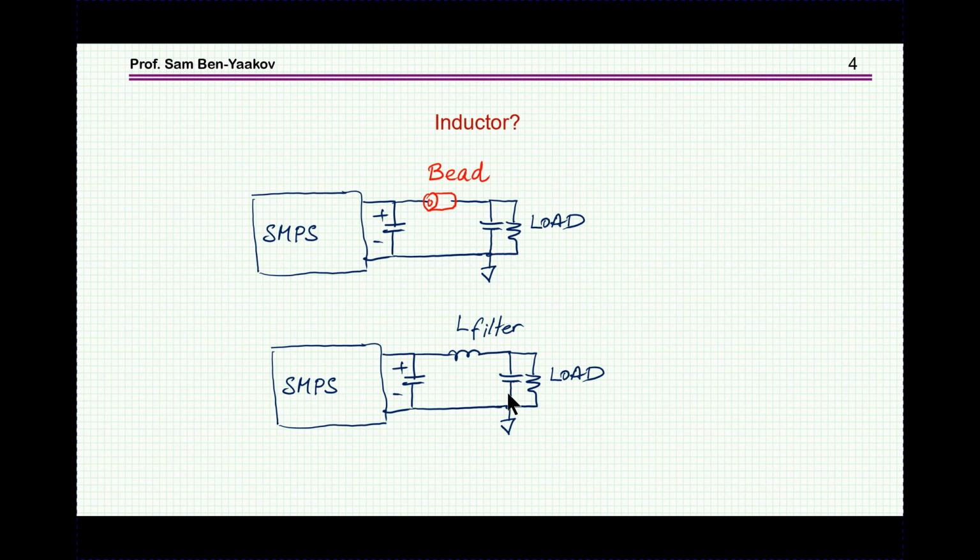And consequently, when you have a step which has all the high frequency components, it'll start oscillating, and here we have interference actually generated by this thing. Of course it's a filter, but around the resonant circuit it's bad news.